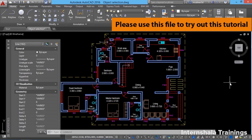Since I have already prepared the selection, I can execute an editing command now, which is called the noun verb method. Now I'll just click on the copy command. Now it will ask you for a base point and a second point. This is the best method to perform such a complicated selection. So that's all about the various object selection methods in AutoCAD. Depending upon the situation, you should be in a position to locate and implement the best suitable method.